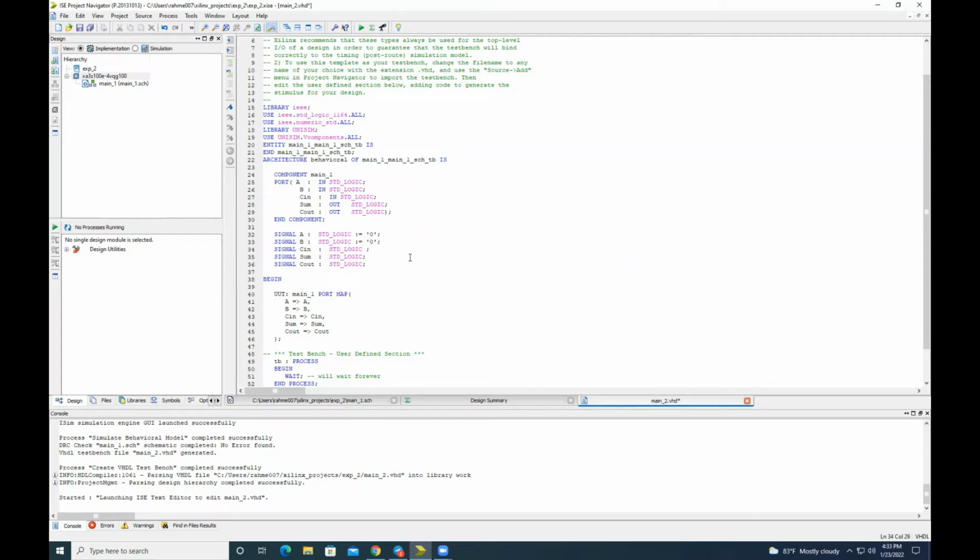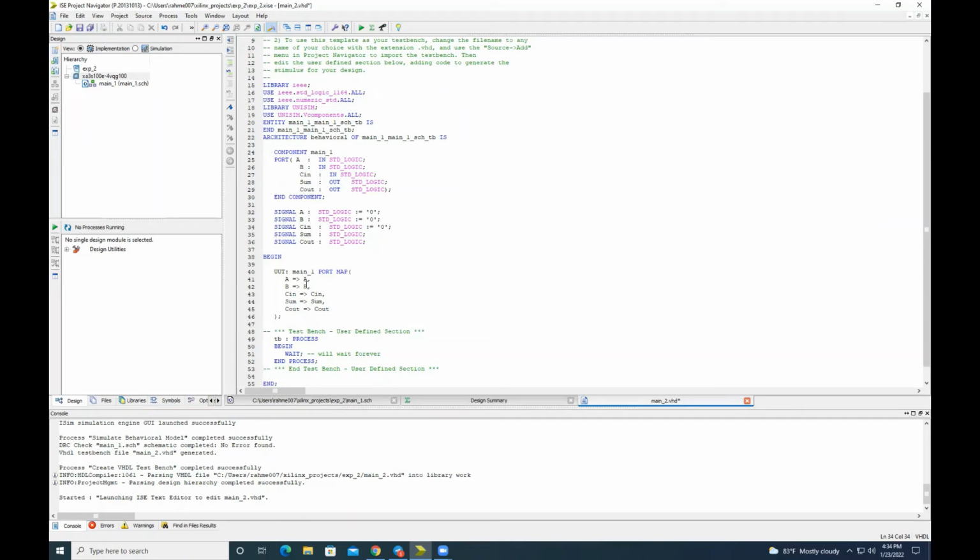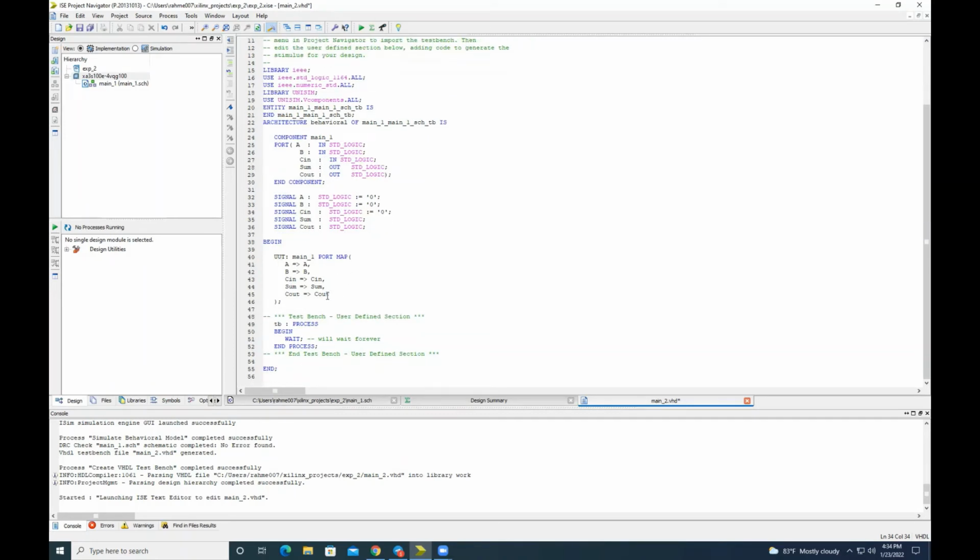It's very easy. So I'm gonna put that here as well, since this is the carrier, right? You don't need to instantiate your sum and ci because they are the output ports. Now begin with the unit under test. And here you have the port map, which has already been assigned. Then you have the test bench.